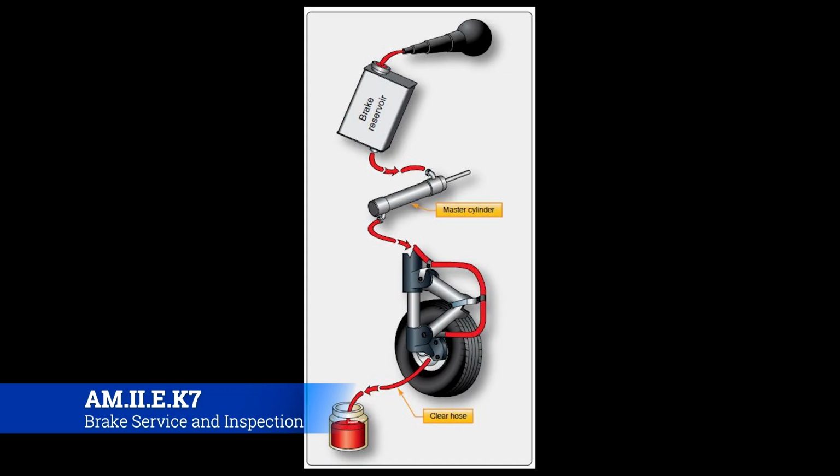Okay, the next big inspection criterion you're going to look for is simply pushing on the brakes and seeing if they have a spongy or soft feel. If they do, it means that there's air somewhere in the line. The brakes should feel hard, because keep in mind you're pushing pressurized fluid through those lines. If they feel soft, the only thing that will compress inside of those lines is air. If it's full of fluid, it won't compress at all, and it'll feel like you're pushing on something solid, much like a push pin or a rod, except this time it's all made out of fluid.